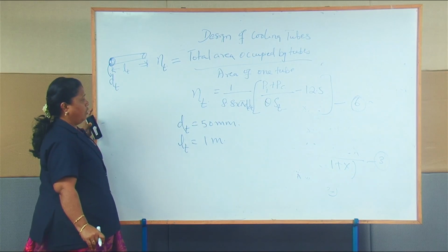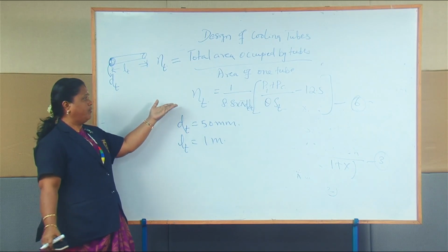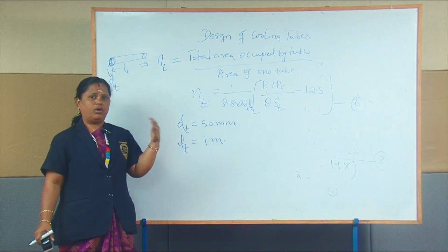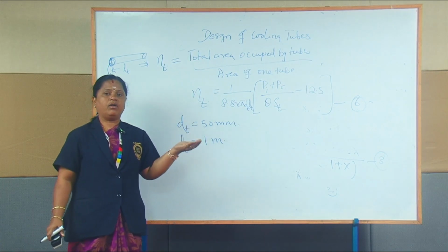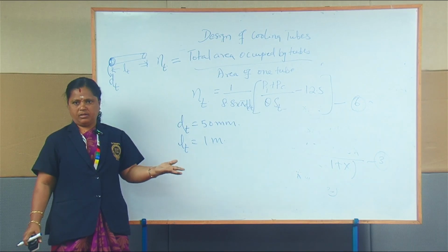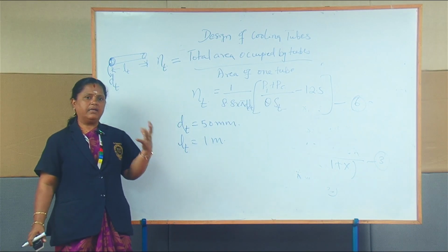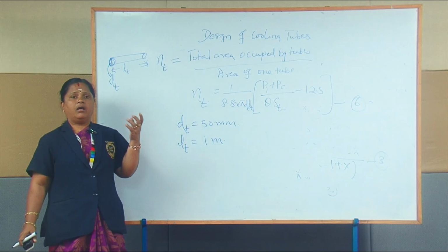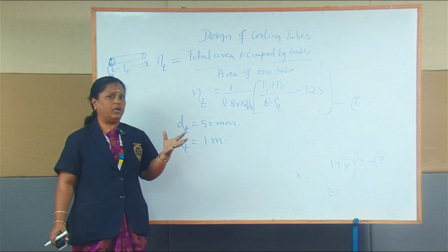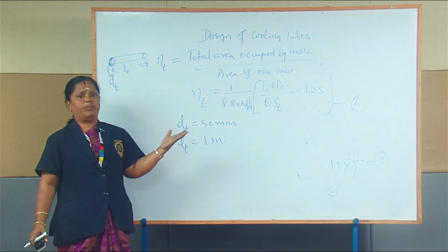Okay. So, I hope you can understand how the number of cooling tubes is calculated, and we have seen why a cooling tank is necessary for a transformer. Huge power heat loss will be there, so we need an oil filled tank. I forgot to mention one thing, there are different methods of cooling, which is a separate chapter, cooling methods of transformer.